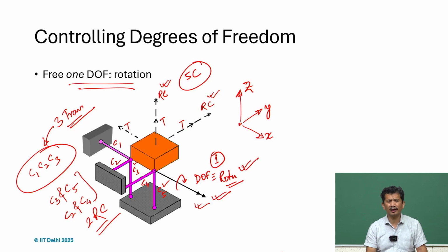So, likewise any design, if any configuration if you want to have depending on the requirement, just by placing these articulated links, and later we call it wire flexures. So, we can replace it with the wire flexures, or we can also think of constraint lines. So, if we suggest a contact, then we can establish the constraint lines along those directions, and if you proceed similarly, what we realize that we can get any configuration with the desired degree of freedom and constraints.